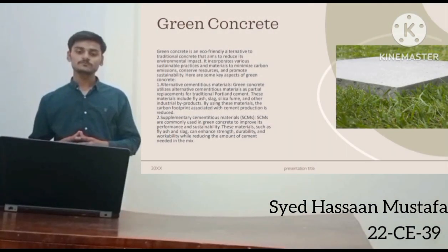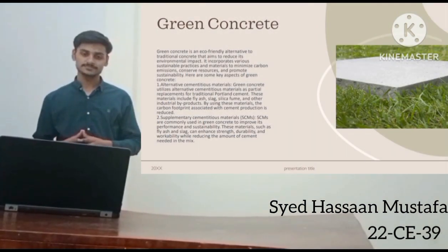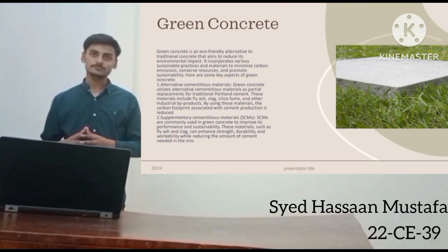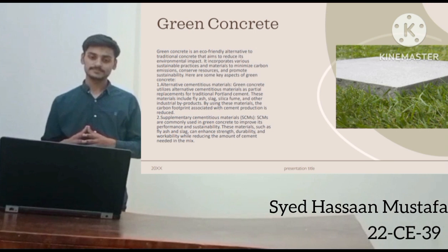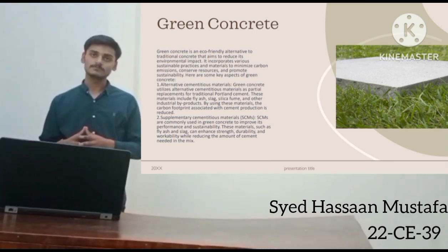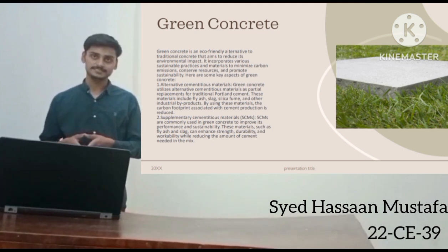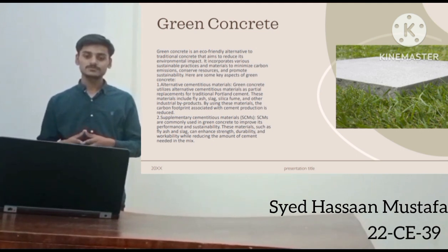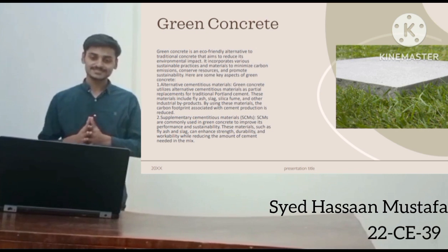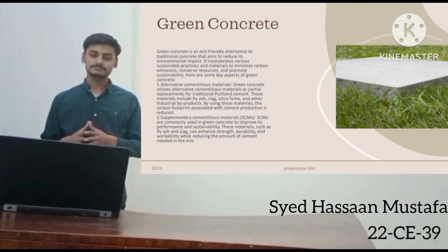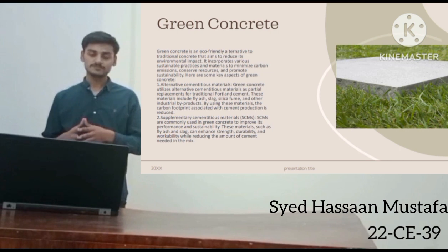Now we are moving to the next point, that is green concrete. Green concrete is a new form of concrete that is being used a lot in engineering construction. It focuses on using eco-friendly materials as a substitute for harmful materials. Now let's look at what green concrete actually is. In green concrete, we reduce the carbon footprint of cement by using industrial byproducts like fly ash, slag, and silica fume.